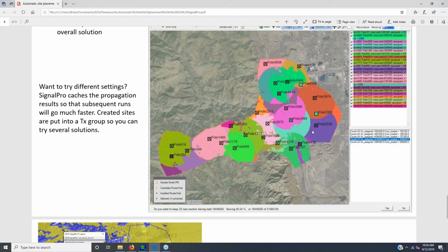Yeah, and so with that, what you're saying is you would actually add that into the pole database before you import that? Right. When you set up your list of candidate pole locations, you would include both of those heights as unique entries in the pole database, so that it'll evaluate each of those XYZ locations as a potential gateway.